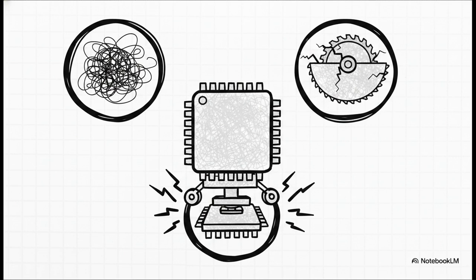Interconnect formation, dielectric deposition, and more CMP processes create metallization irregularities. Later steps, like wafer backgrinding and dicing, actually physically damage the silicon bonds at the wafer edges, creating surface states and whole new leakage paths. Then, the packaging process itself introduces mechanical stress that interacts with all those underlying atomic defects we just tracked. It is, quite frankly, a cumulative nightmare for your reliability.